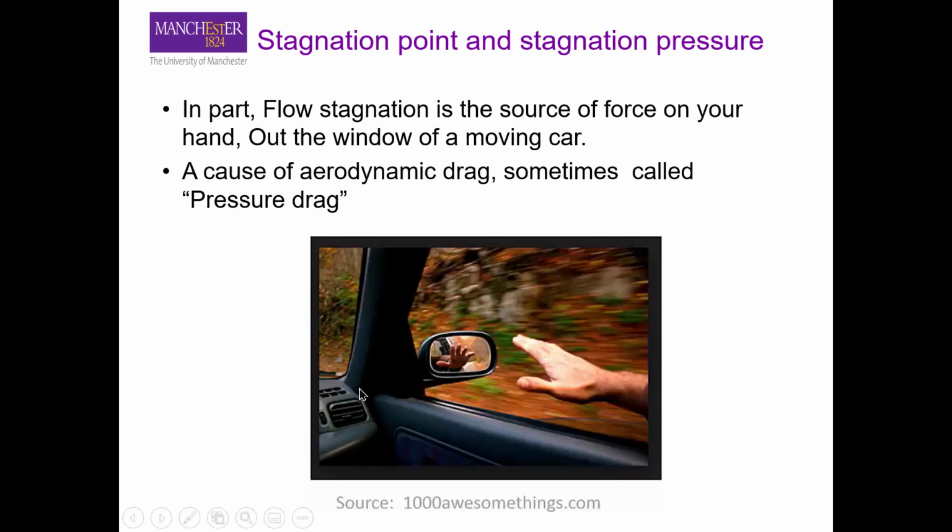And so that you can relate it better, for example, if you take your hand out of the window when the car is driving, you feel a force on your hand. And that force in part comes from the stagnation concept or stagnation pressure. It means that the high velocity air that is moving comes to a standstill at the palm of your hand, and that is the conversion of dynamic pressure to the static pressure that you feel on your hand. Okay, and in aerodynamics, for example, we call this pressure drag, and it is different from viscous drag that is due to the velocity effects.